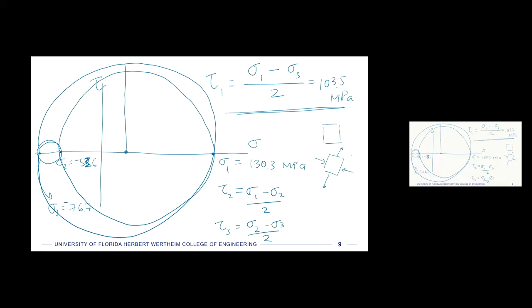And so if we rotate this 45 more degrees, we'll be at one of the principal shear planes. If we rotate it minus 45, we'll be at another one. Okay. So for every rotation to get the principal normal stresses, there are two shear stress planes that could be a maximum, right? Minus 45, plus 45, which correspond to minus and plus 90 on the Mohr circle.